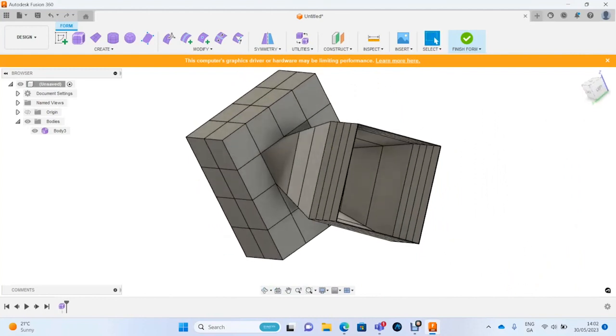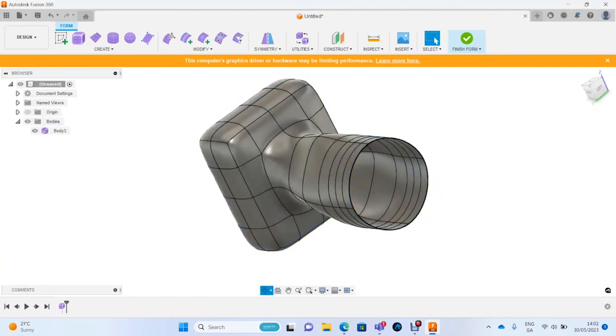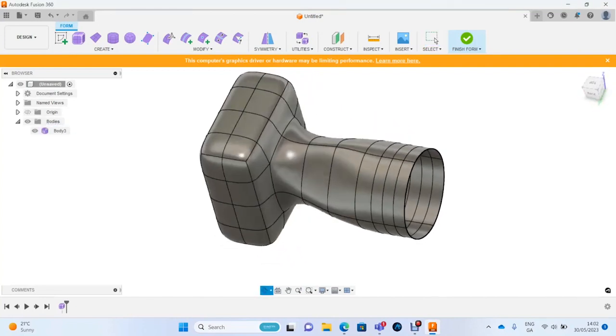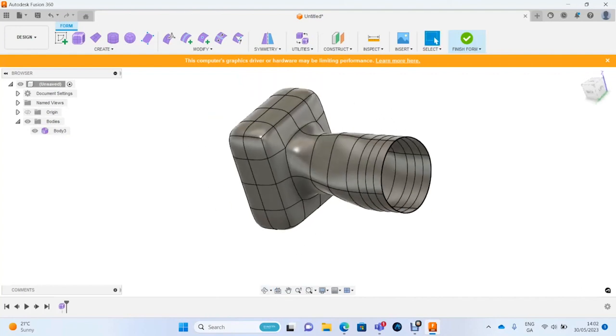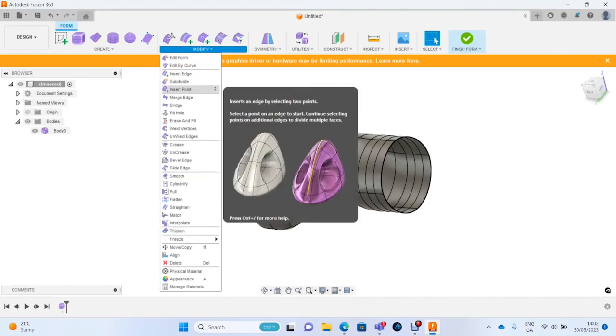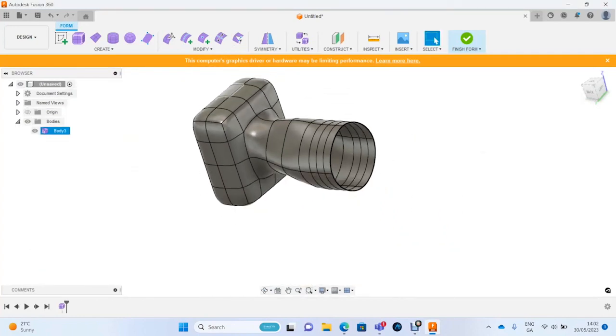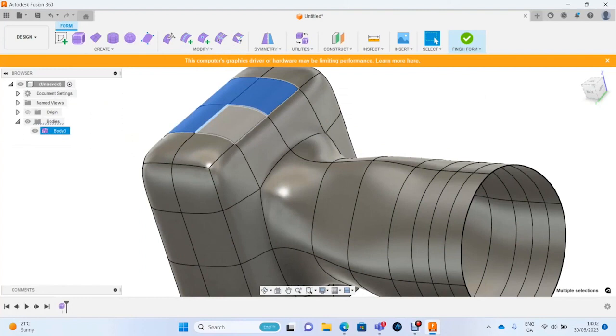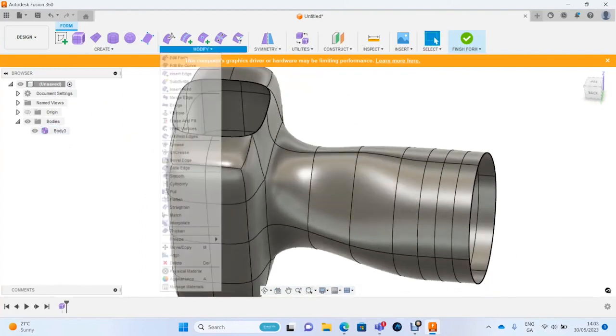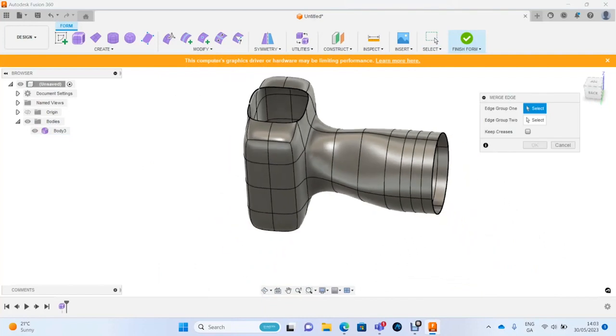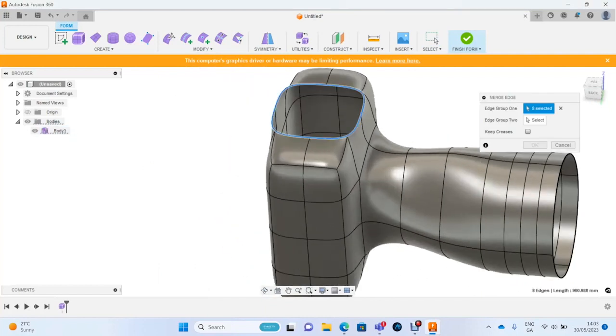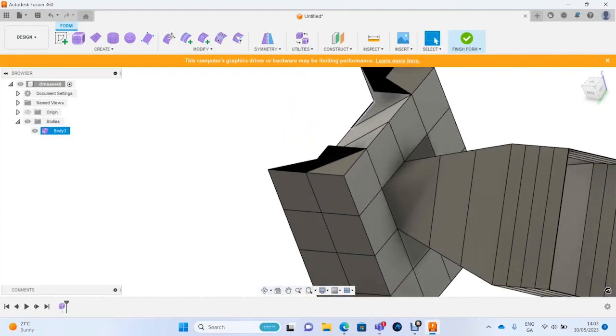And if we go back to, again, select the body. So we can see now that created a fairly neat bridge. Not perfect, but we will look at the merge edge tool now. This is useful if you have holes like this. You can select multiple. You can do chain select, but generally you'd select a few. This will create problems because these edges won't be welded to the. I'll just show you now. So it's going to create a mess of our geometry.